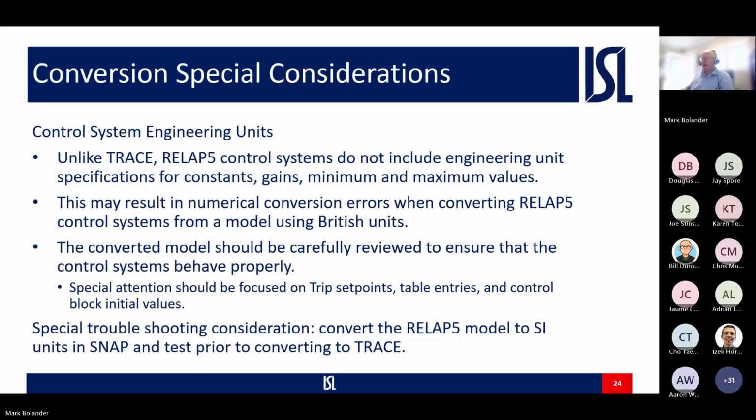All right. So that last little bit there on this slide, I think we've already covered that. If you're having issues, one thing that you can do to troubleshoot is to convert your RELAP5 model to SI units. In some cases that helps, and in some cases you're just going to have to be wary of what's going on there.